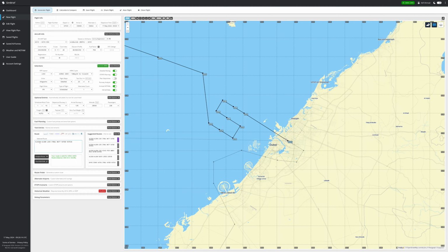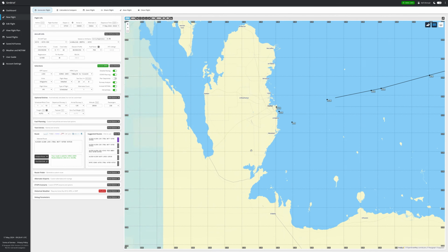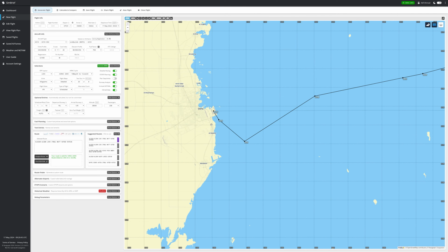So this is the SID, ALSE2M, and this is the STAR, VUTE3E. So just to bring one thing to your notice, if you look at this flight plan, the last waypoint is VUTEB, which is this, and then there is a STAR, arrival procedure. And all these waypoints are not coming over there in this flight plan because they are part of the STAR. Similarly, it's for the departure.